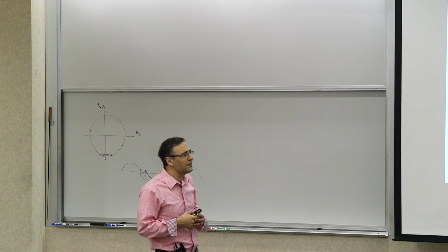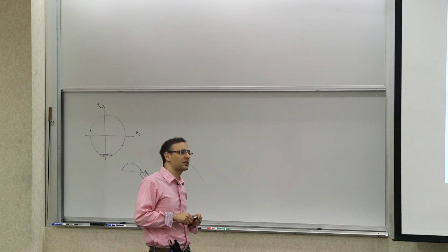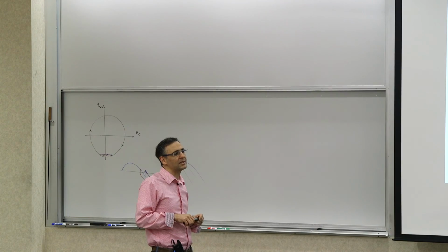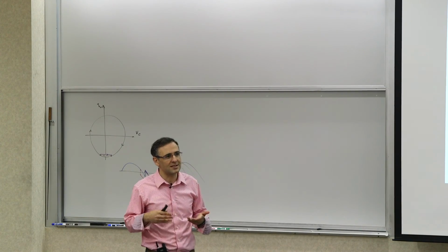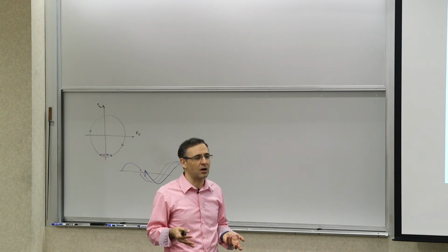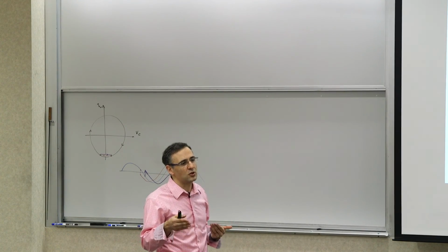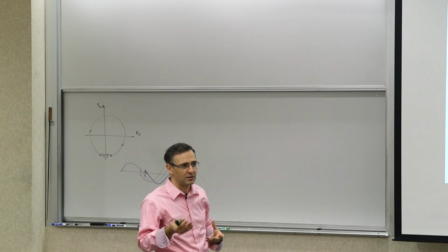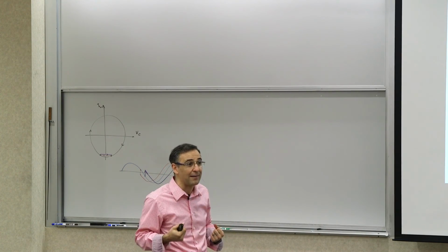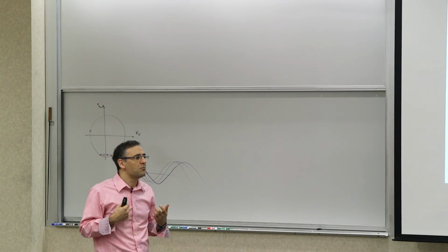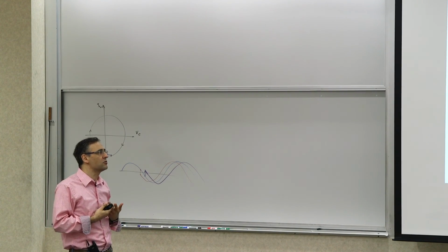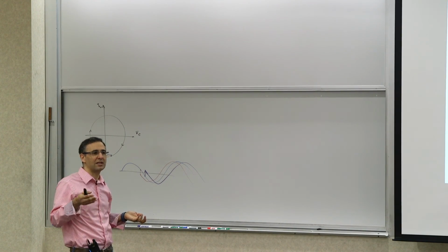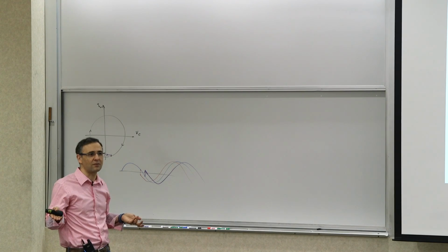So yeah, it's not very difficult to calculate analytically. It depends on the kind of oscillator. Some of them are more difficult, but at the end of the day, you will probably run a simulation to get an accurate model of the ISF, because your ISF will depend on the dependence of the capacitances and all of the nonlinearity of the device itself. So all of this is captured in the ISF. And because of that, most often you may not want to do it analytically, but generating it in a simulation is a pretty straightforward thing.